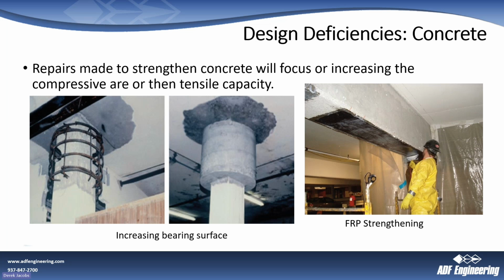If you have a beam, like this concrete beam here, if it's undersized and you need to strengthen it, you can strengthen the tensile ability of it by either deepening it, adding more reinforcement, or, this is kind of nifty, they add this FRP, this fiber reinforcement, these tensile strands, essentially gluing those to the underside of the beam to increase its bending capacity in that way.